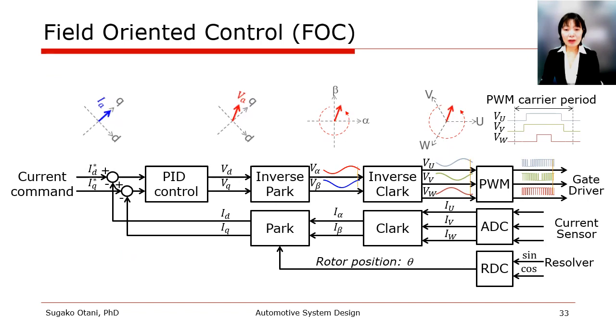Field-oriented control algorithm (FOC), as shown here, is the most popular type of algorithm that can achieve highly efficient motor control. To calculate the optimum PWM duty values, FOC contains compute-intensive functions, including coordinate transformations, series of matrices. Therefore, MCUs for motor control are required to have high computing power.